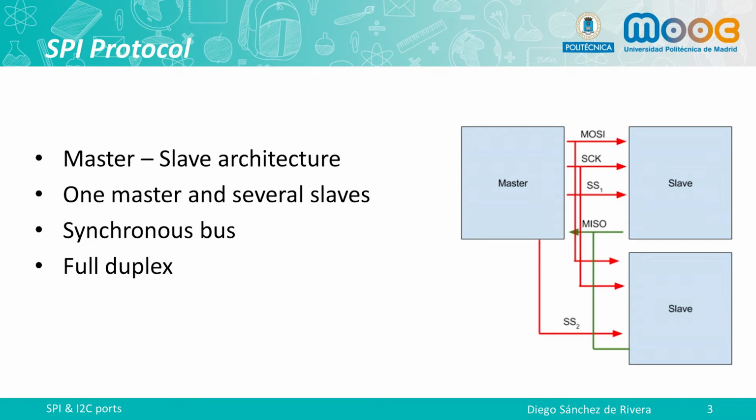Serial Peripheral Interface (SPI) is a synchronous serial data protocol used by microcontrollers for communicating with one or more peripheral devices quickly over a short distance. It can also be used for communication between two microcontrollers. With an SPI connection, there is always one master device which controls the slave devices. The communication over this bus is full duplex.